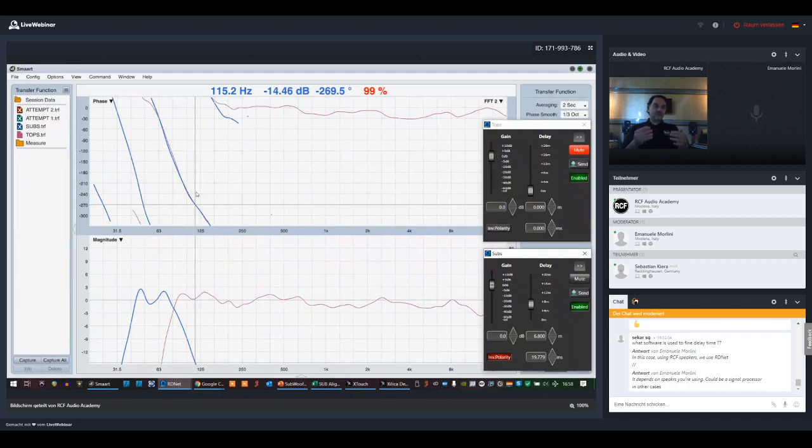according to the phase behavior of these sound sources, we are aligning the system exactly in the same cycle, because we are in the same cycle in the crossover zone as well as in the same cycle in all the surrounding frequencies that are in the crossover area.